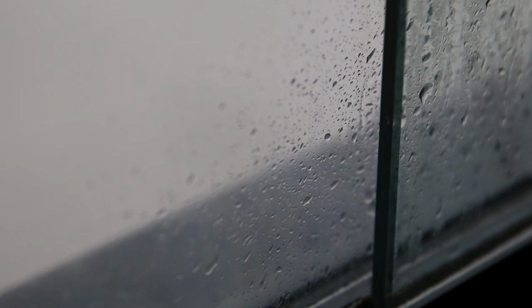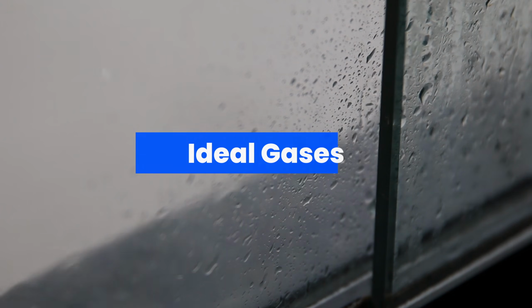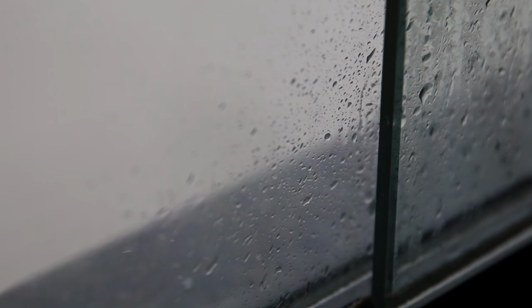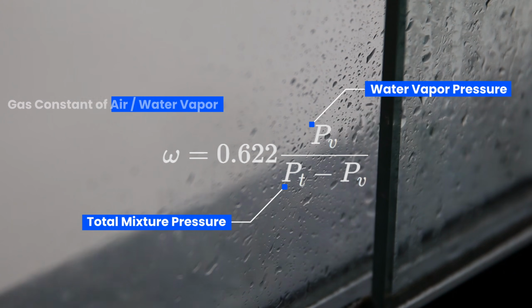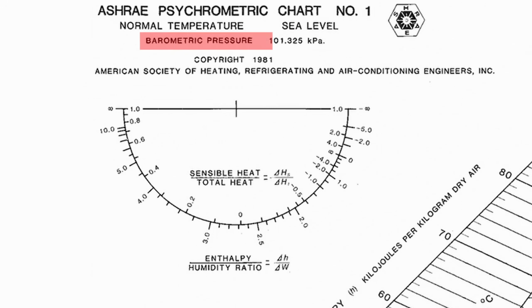Now, if we think of both dry air and water vapor as ideal gases, we can come up with an equation that links the pressure of water vapor to its partial pressure. That's actually why the psychrometric chart often uses the humidity ratio. It's directly tied to the partial pressure of the water vapor. It's also important to understand that each psychrometric chart is created for a specific total pressure.